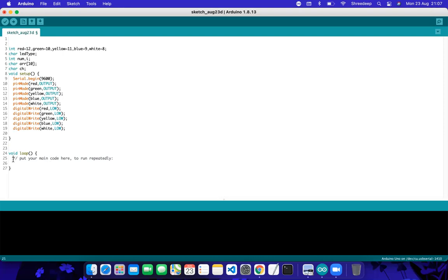So now within Serial.println, I'm just writing this code in a different manner, just to make two things happen parallelly. Okay, just watch me carefully. So we know, Ravi, that if Serial.available, it means that something was pressed. Serial.available greater than 0, or equals to nothing, it means that Serial.available is 1. That means at least 1 character is available from your keyboard in the serial buffer.